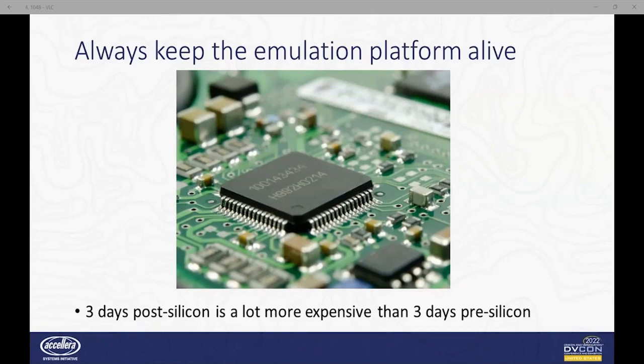You may have to put in some address filters to block register accesses to the analog blocks. Make the timeout counters programmable, since the silicon runs a lot faster than the emulation. The key is to run the same software binary on the silicon and the emulation platform without recompiling. Nothing is really hard if you plan ahead of time.